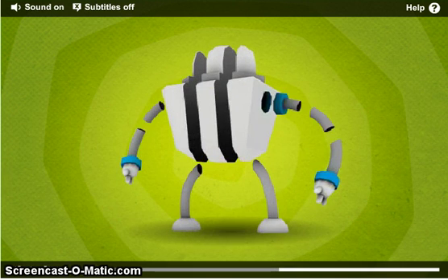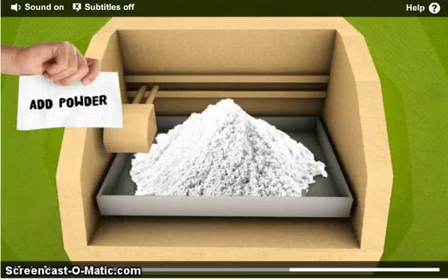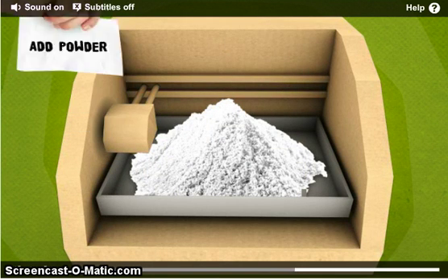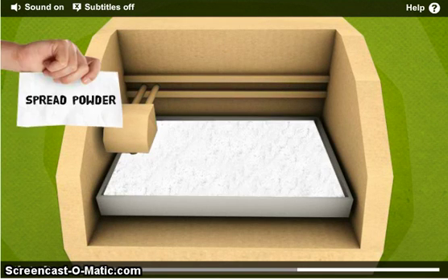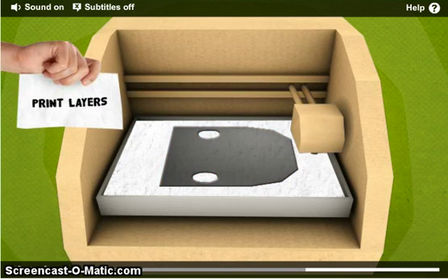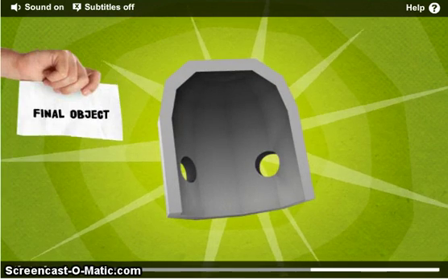Software slices the imported CAD design into lots of thin cross-sections. The printer then prints those cross-sections one at a time. Instead of paper, each slice is printed into a thin layer of powdered plastic, and in place of ink, they use heat or chemicals to fuse the powder into a solid. The process is repeated for every layer until you have a complete 3D object.